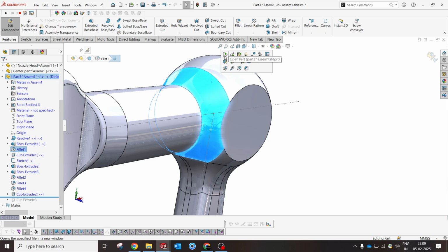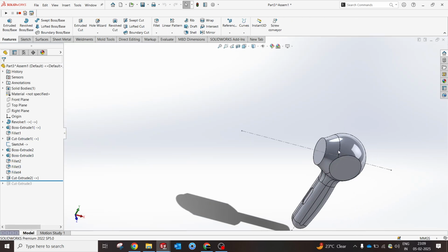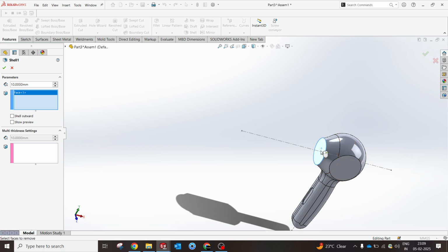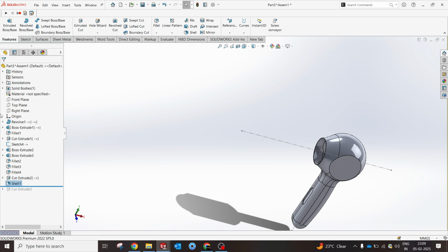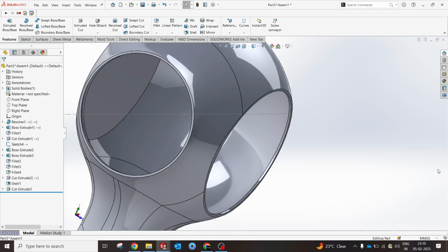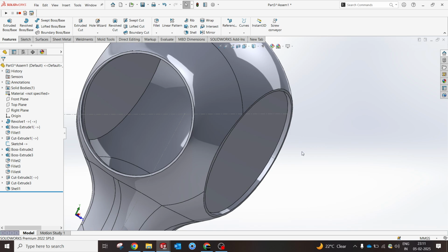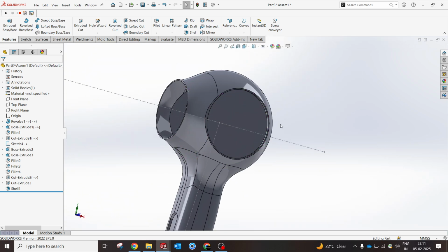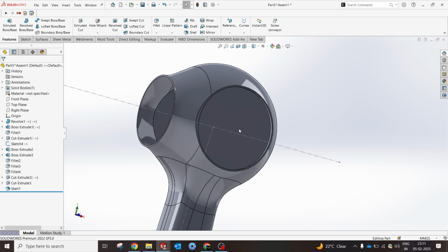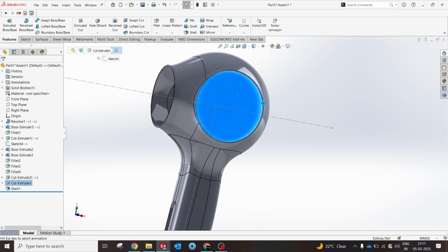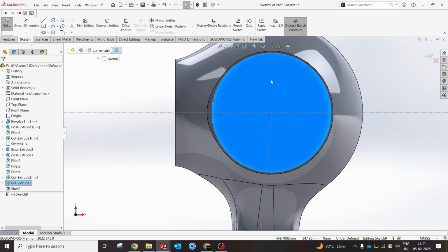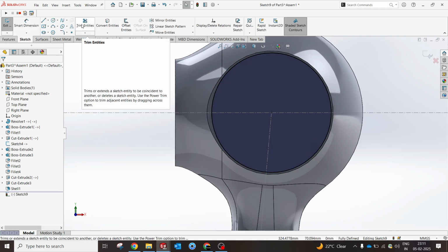So what I will do, I'm just opening the part alone in order to select. So shell we can do, around 2 mm thickness again for this. Yeah, so now we will do an extrude. Okay, we'll remove this something. Yep, only one side we are doing, so I'm just flipping the shell so that I have an area where I can create a vent system, the support.